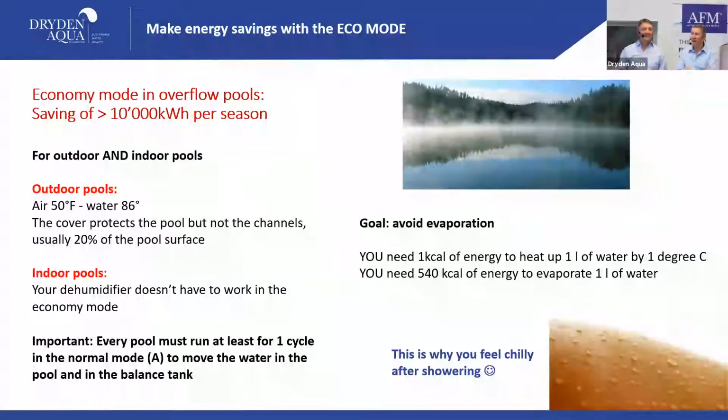Okay. So yeah, you all know this. When you come out from the shower, your skin's wet, you're starting to feel a little bit of cold. And the reason for that, even when your room is warm, is because the water on your body wants to evaporate, and it does it by pulling energy from your body. That's why your body cools down and you feel cool. As soon as you start drying up, you're fine again because the water's gone. And that's the same evaporation in a pool. And that's true if it's an indoor pool or also an outdoor pool. It's always the same. This is where you lose your energy.